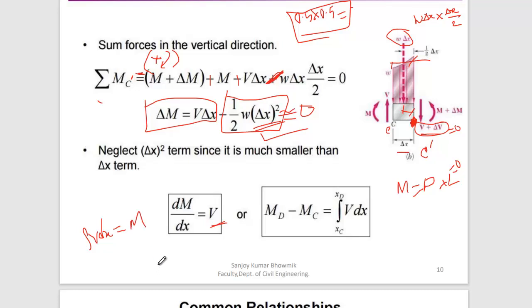So the mathematical operation we see here is that integration of shear, that means the area of shear, gives us the value of moment. Similarly, the area of force gives us the shear. Our main target is usually to draw the shear force and bending moment diagrams.